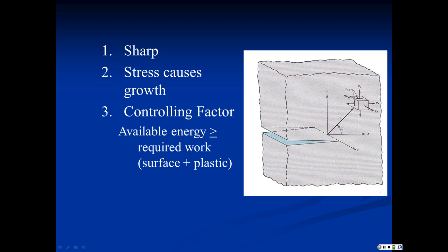When you make a surface, you're going to increase the energy of all the atoms of that surface, and so you have to do work to make a surface. Also, you may have plastic deformation occurring, or viscoplastic deformation, and those processes consume energy, and so that work also has to be done. So there's a fundamental work that's required for fracture, and if there's enough energy in the structure to do that work, then the crack can grow, and if there's not enough energy, then the crack doesn't go anywhere.